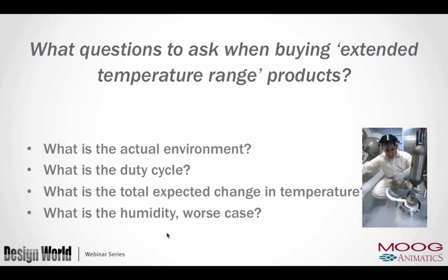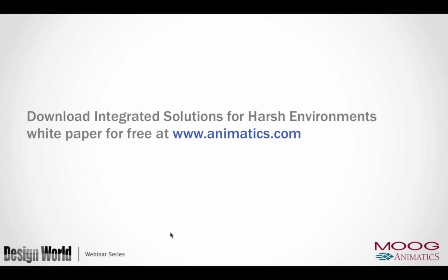Does it reach the point where condensation actually occurs on surfaces? I can tell you for sure that in a normal office environment, in most working environments, if you set a cold motor on your desk, will humidity condense on the surface of that motor? If it's a warm motor and running, or if it's at room temperature, you should never get condensation on the surface. Obviously, if you have a glass of ice water there, it may condense, but that ice water is near freezing or below freezing. So normally your motor will not be below freezing, and it shouldn't condense on it. Okay?